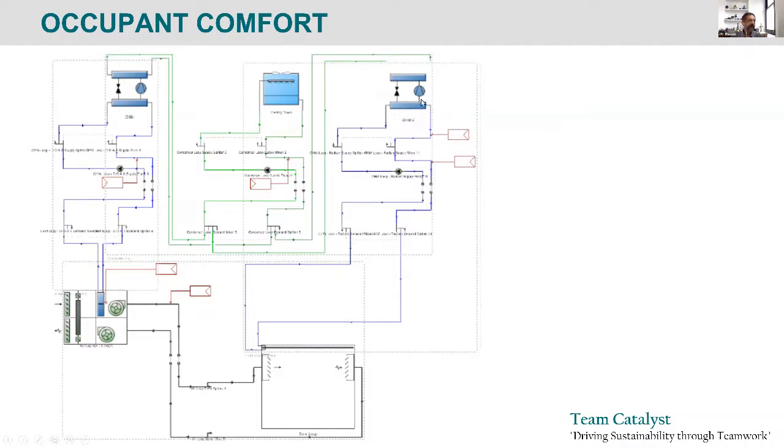But the other way is that you put a heat exchanger in this loop, and then from the heat exchanger, you supply the chilled ceiling, okay? And the heat exchanger then allows the 6-degree water to change temperature to 13 degrees or whatever it is you want, and then go from there. So there'll be a separate pump in there. I haven't shown you that, but if you search the internet, you see designs and talk to your mechanical engineer, there will be some options there.